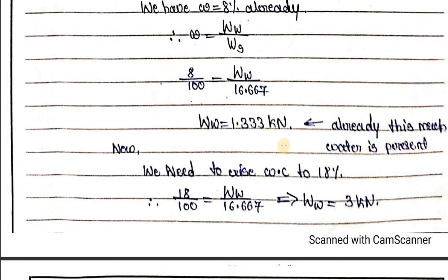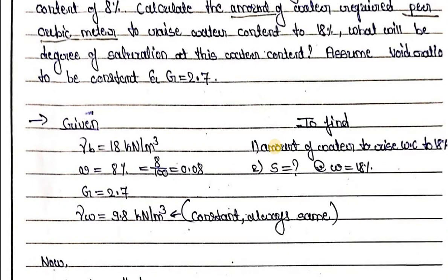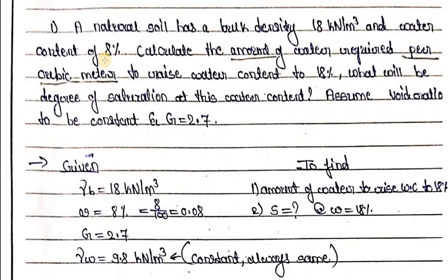But remember what they have asked: already 8% water content is there. How much amount of water is to be added to raise the water content to 18%.